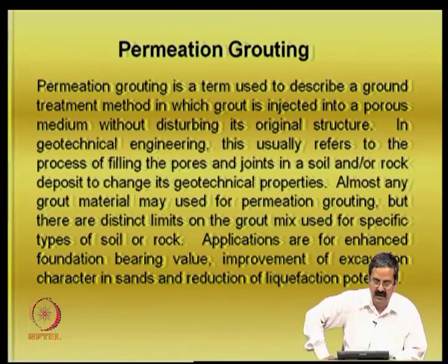As I just mentioned, we have another type called permeation grouting. It is a term used to describe a ground treatment method in which grout is injected into a porous medium without disturbing the original structure.